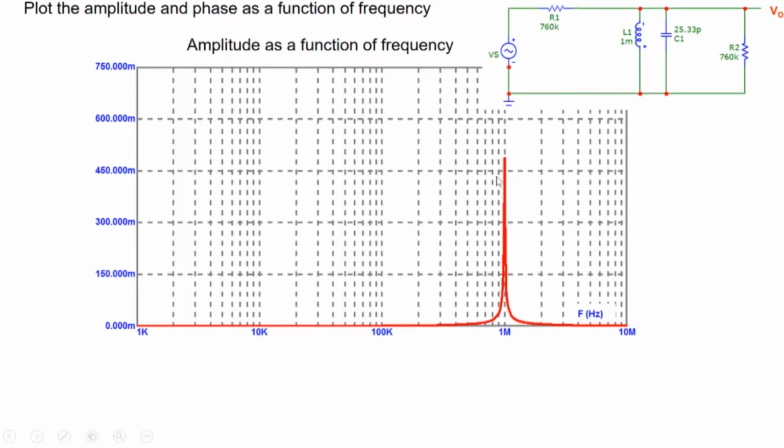So, whenever we have a frequency selective circuit, you can call it a filter. And here we can see that it's like a band pass filter. Band pass, there's a small band of frequencies which it allows to pass around that 1 megahertz here. So it's like a highly narrow band filter. If my filter were to allow anything from 100 kilohertz to 10 megahertz to go through, that would be a fairly broad band pass filter, but this is a highly narrow band pass filter here.